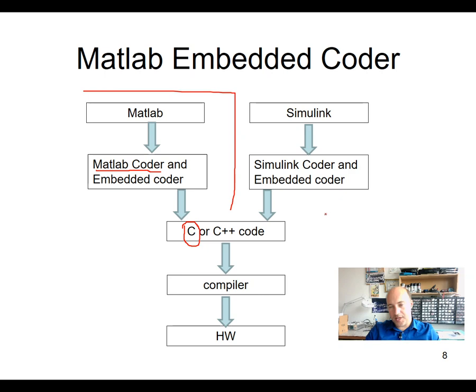And then in 2 weeks we will do the similar approach with Simulink. First of all, we will see in Simulink how we can actually create some model of a system. I think the most basic system that we will create will be that we will blink with an LED. And then by using Simulink Embedded Coder, we will run this code on the development board, and we'll see how it runs.